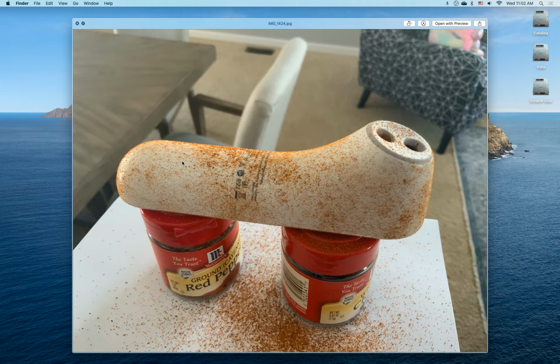So the thermometer is made out of a white plastic and it's kind of glossy. So I needed to fight the problem of this whole thing being just white and also being glossy. What I used here was simply some cinnamon and I sprinkled it over it. That helps the software to see more of the geometry. Otherwise, it would just see something that is white. Plus the cinnamon or the spice, whatever you will use, also helps fight to a certain degree the glossiness. You can see the glossiness right here where this reflects the light from the window, or the same here.